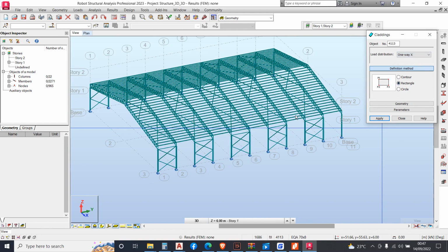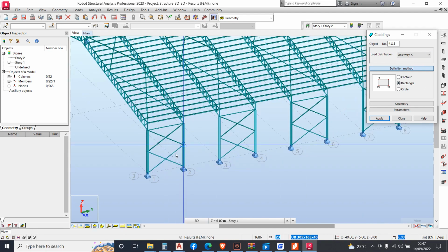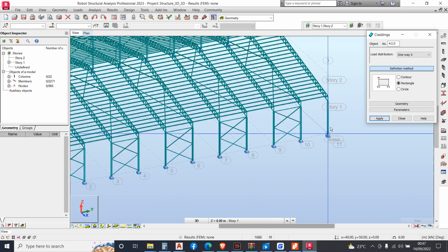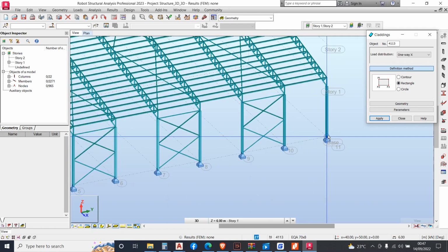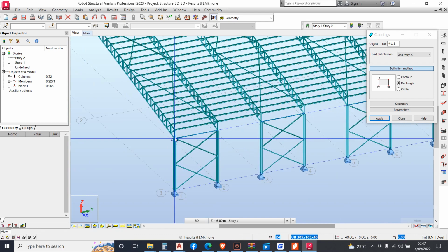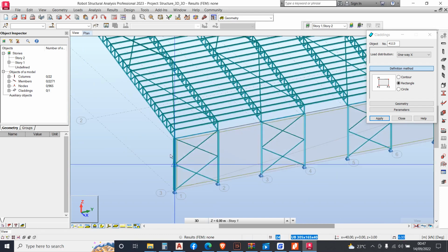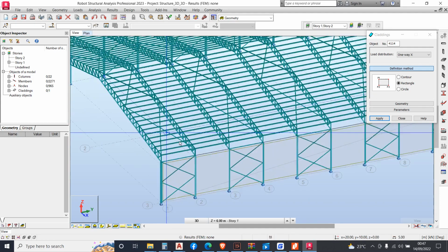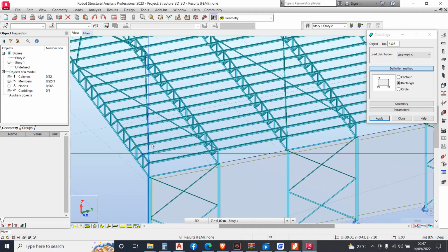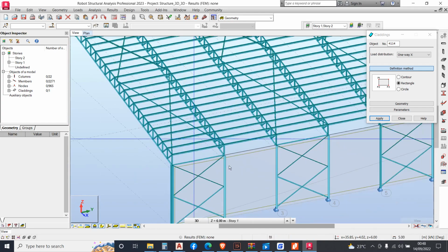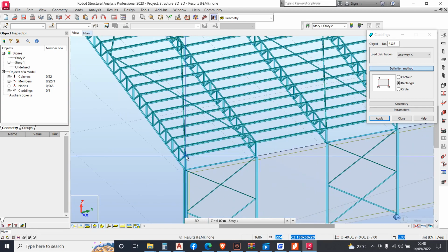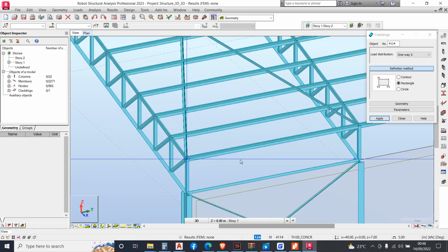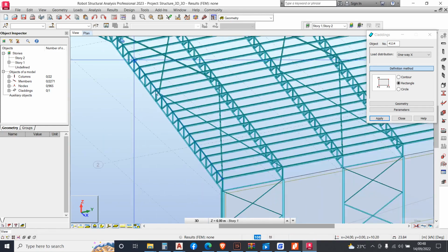One way we'll add the load, maybe one way X. So the first direction you usually pick is your X. So we'll tell it that okay, this is X. Start here. Good. You have that. So here we want, since I want my load to lie on polyline, load to be distributed to the polyline, I'll pick here. I'll go this direction as my X.